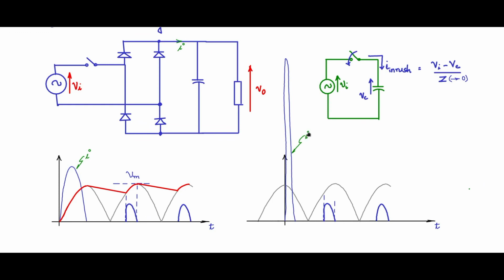amps. So this is the current here, and the capacitor voltage quickly builds up to this value, and then the diode cuts off, and then the steady state starts. So you see that it is during this time the entire problem occurs, and during this time itself the diodes will blow, and you will not be able to take it to the steady state.